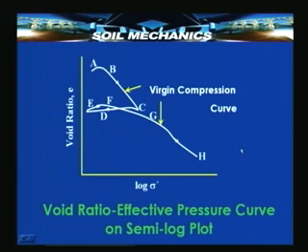It is always good to have such a graph where the relationship which is actually non-linear gets converted into a relatively linear relationship. That is, void ratio versus sigma dash graph was non-linear, whereas void ratio e versus log sigma dash graph is relatively linear, and it now becomes much easier to establish a linear relationship between e and sigma dash, which is very convenient to use. Let us see the next slide. This is how we establish the relationship between e and sigma dash.